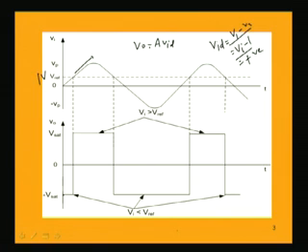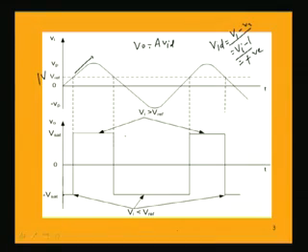That means as soon as the input voltage Vi becomes greater than the reference voltage, we will be getting an output which is positive, but that will also be saturated, because it cannot go beyond the supply voltage. Around 14 volt is the typically obtained value at V saturation. So, around that 14 volt V saturation, but positive, we will be getting at the output.